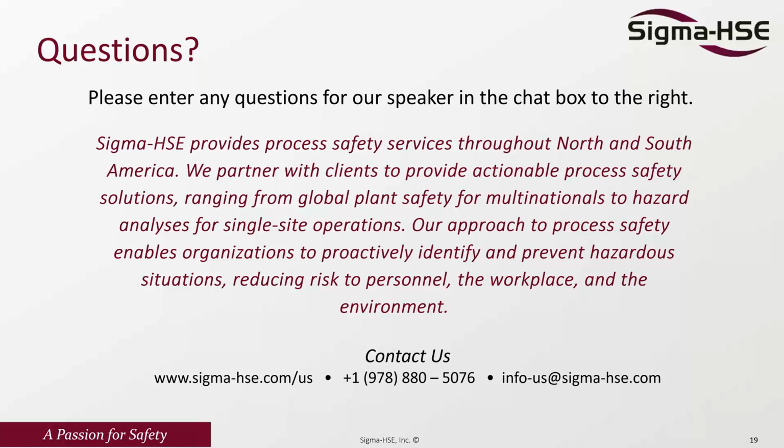Yeah, that's a good question, and there may be some temptation to do that. But at these early stages of the PHA life cycle, you're not going to have all the process safety information that is required for a good study. Therefore, you will not be identifying all the risks and putting mitigations in place to control those risks. And that can lead to injuries, environmental insults, or monetary losses after the project is commissioned.